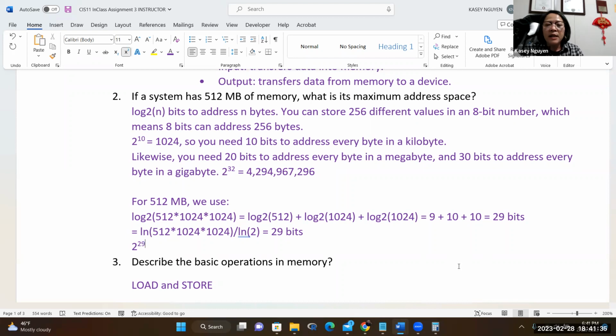And so for number 3, I touched on this prior to the address space. We talked about load and store, right? Read and write to memory. And the major difference is for the read, it uses the read signal, and write enable for the store, and it uses the MAR for address, and it uses that address to find the actual data, and it uses the MDR to get the data.